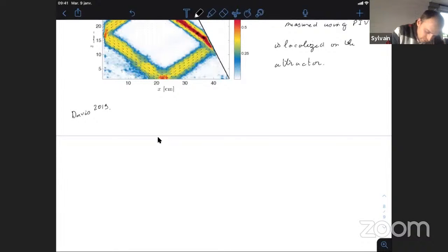From the measured velocity field V, we have been able to estimate the injected power and the dissipated one. In fact, from the measured velocity field, we can estimate the pressure using the linear Navier-Stokes equation, and then calculate the injected power. We can also estimate the dissipation rate.